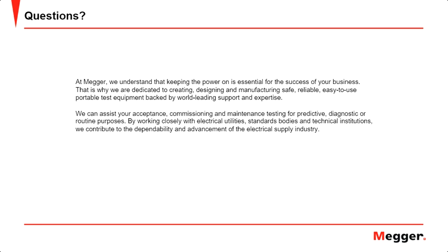And I would like to add something to that as well. When you are doing online PD testing, the given thing is that you have to have sensors mounted on that specific cable. So there is a lot of costing involved, a lot of work practices involved with it, and ultimately everything comes down to the budget, right? If you have the budget to do it, and online monitoring is something similar along those lines, you have to have HFCTs mounted at every so and so distance or every termination in that cable, which is not a very budget friendly thing to do.